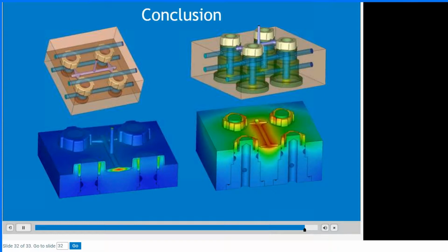Injection molding is a process of heat exchange. Managing this process is critical to part quality and minimizing production costs. Performing mold thermal analyses on new tooling allows mold designers to evaluate potential design and process challenges prior to mold building and production. Depending on polymer materials, injection pressures, and production cycles, designers can determine what mold steels to use that will reduce production costs and improve molded part quality.